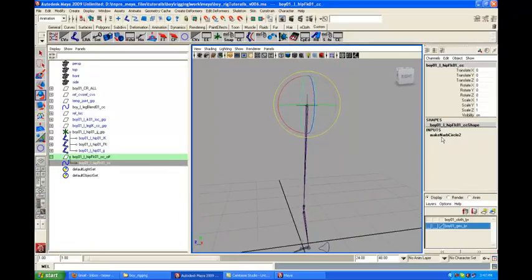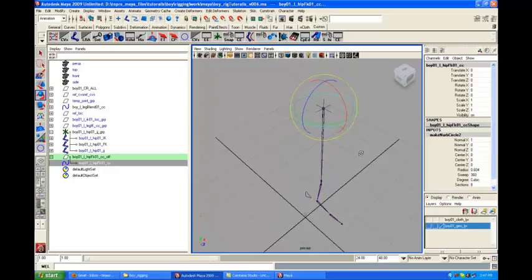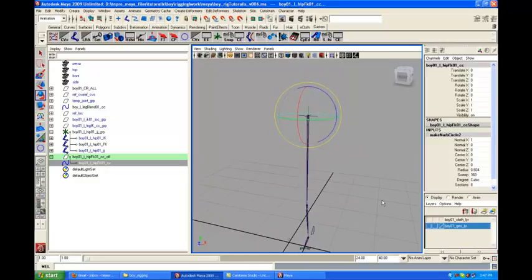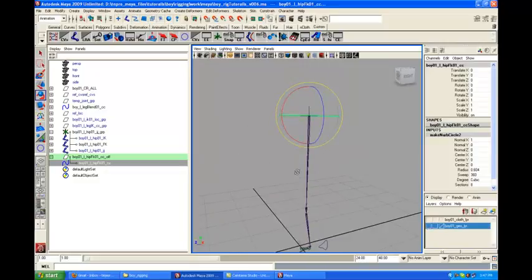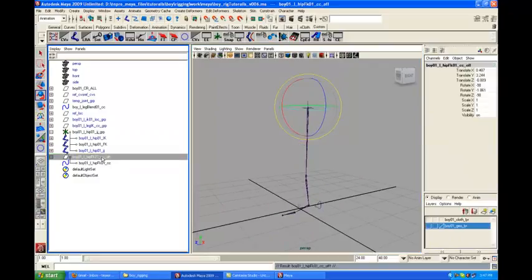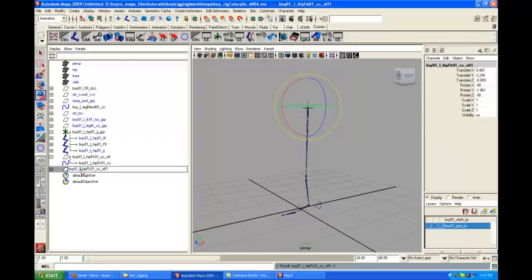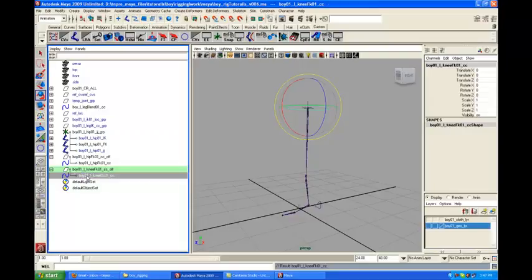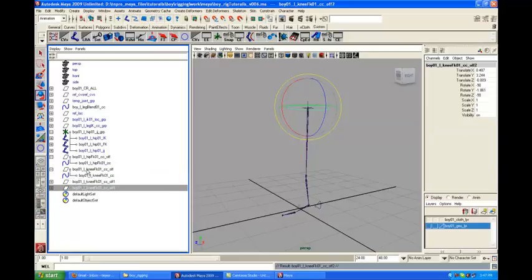Now what we need to do is go to the curves, make X to 1 and Y to 0 so it faces accurately. Okay, so let's duplicate this one time. Let's make it knee, FK01_CC, and let's rename it knee. Control D twice.